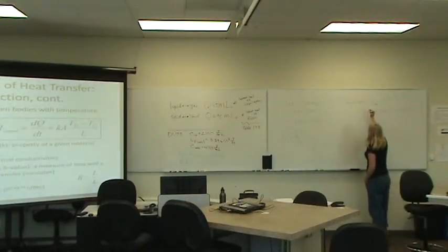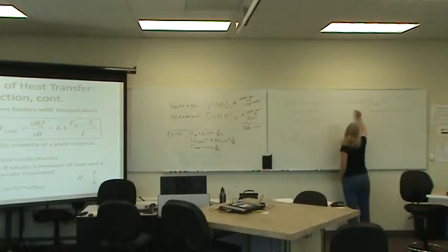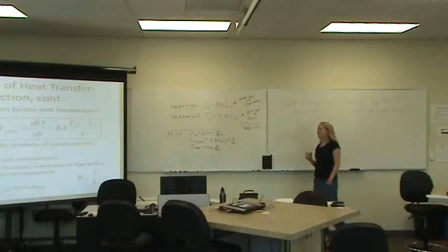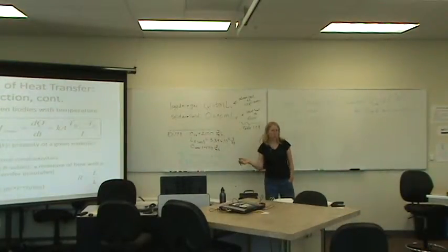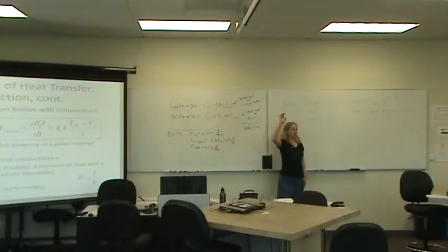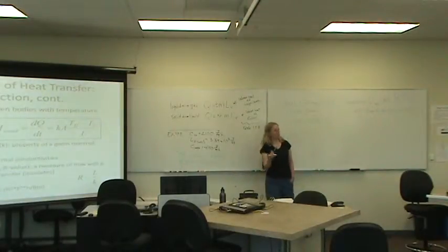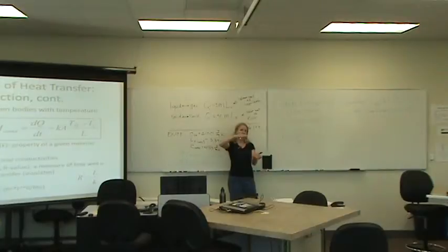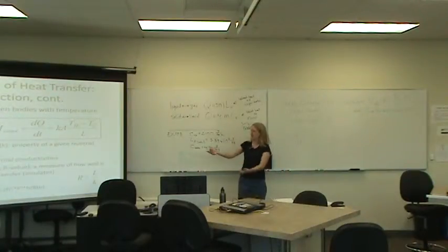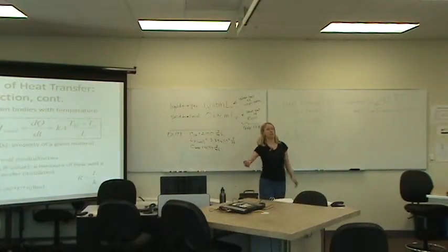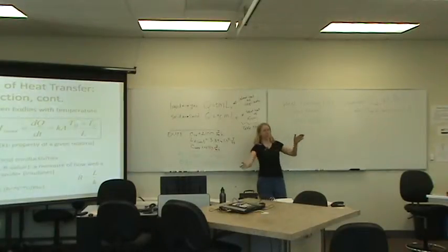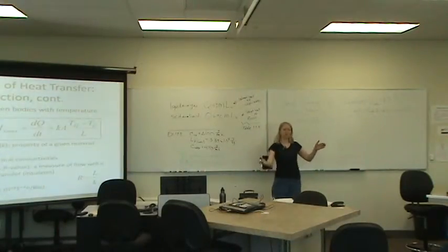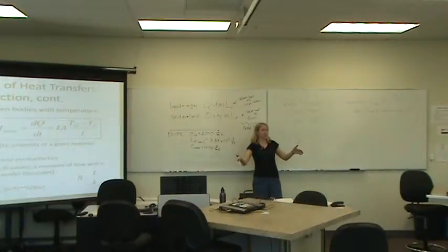Thermal conductivity values can be found in table 17.5. All right, thermal resistance, R value. Anyone in here bought that big pink insulation for their house? It's rated based on the thickness, right? If it's thinner, it's like R15, the thicker stuff's R30. What is that R number? It's actually the thermal resistance. It's resisting temperature transfer through the material. Obviously, the thicker the material, the more resistive it is to heat transfer.